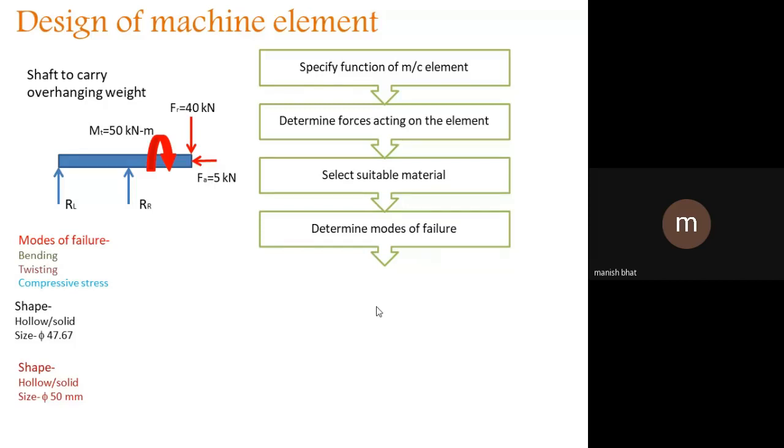So due to bending, bearings will get affected. Bearings are always used. The shaft gets bent, but due to bending of the shaft, bearings will fail, and failure of a bearing can be known by the noise of the bearing.